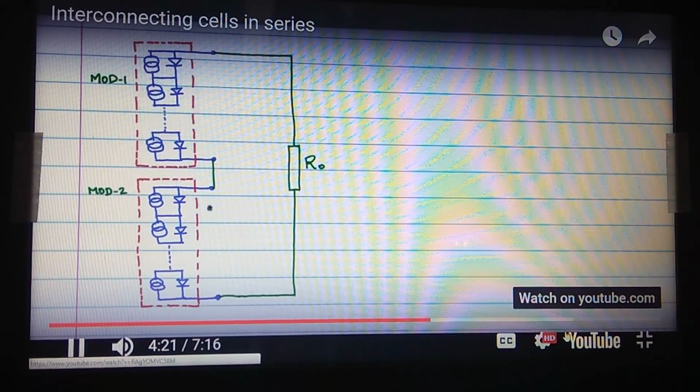Now these can be protected with a bypass diode, because the voltage of the PV cells in series in this PV module will be high. It will be of the order of 35 volts to 40 volts, and it will be much greater than the cut-in voltage of a single diode that you would put in here externally, and that will definitely work.